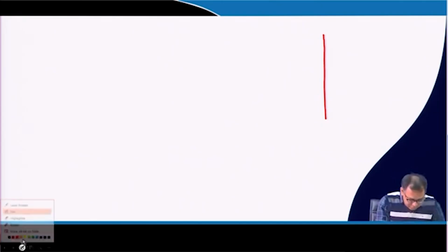If above the point of rotation and below the point of rotation, the active passive zone will change. But in Terzaghi's analysis, I have shown how we can get the net pressure distribution in such a case, but here this pressure distribution is assumed. So, if I draw that assumed net pressure distribution.